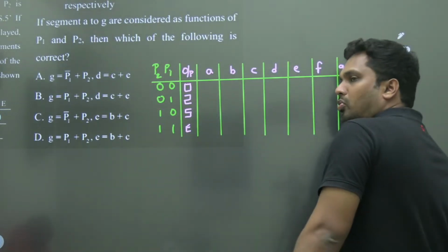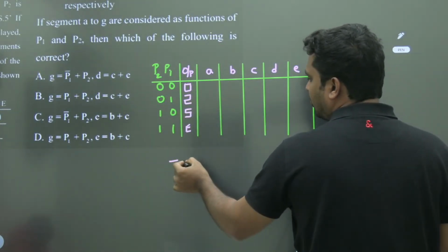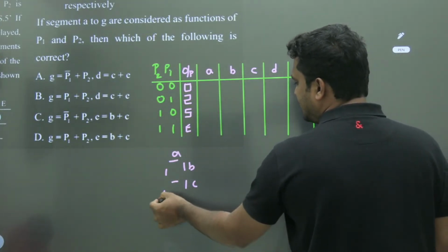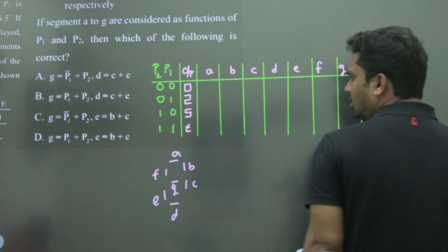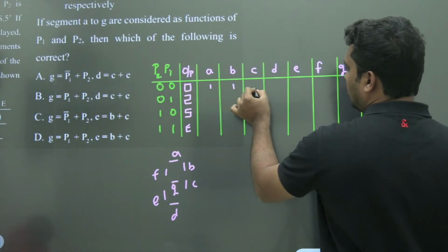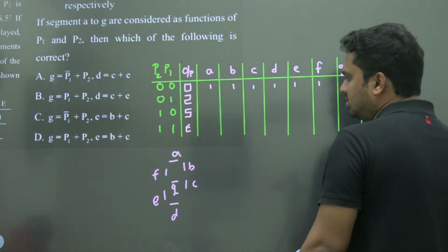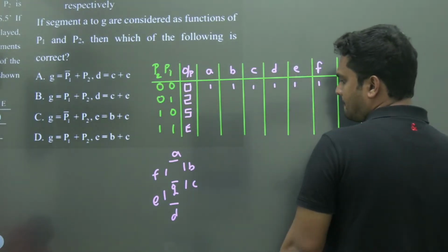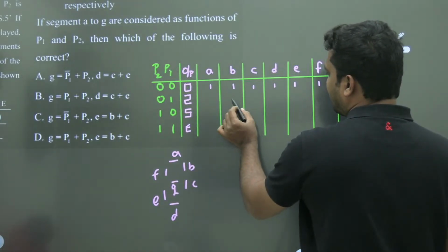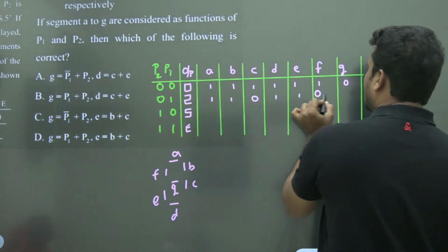If nothing is pressed, it is 0. The LEDs are named A, B, C, D, E, F, G. You can neglect the Z. All will be 1 except G. Next, for 2, all will be 1 except F and C; F and C will be zeros, remaining all will be ones.